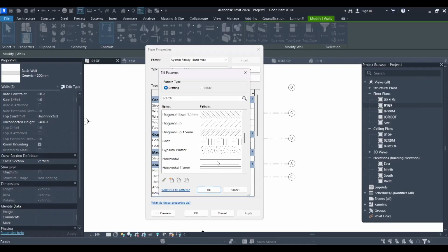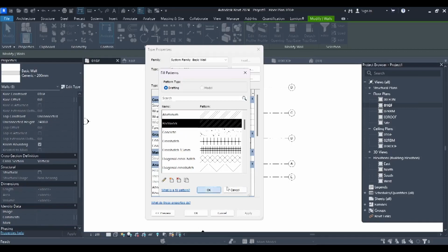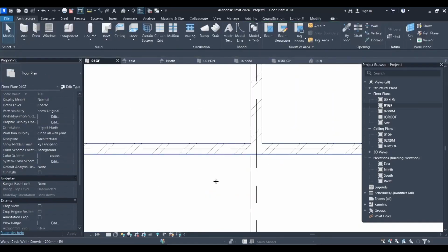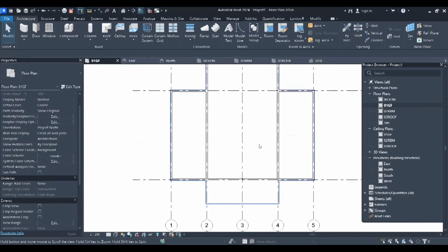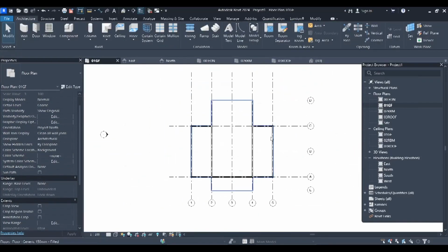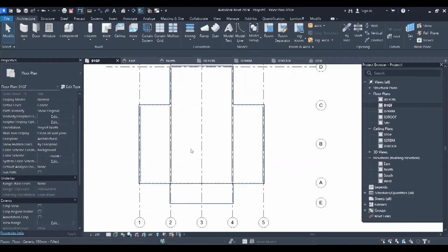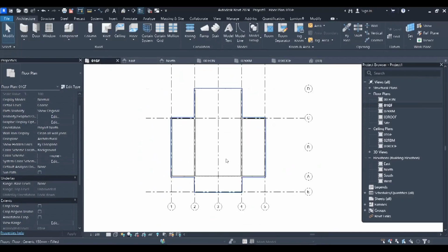Now let me say I want my wall to look like steel, or aluminium, or brick wall. Let me choose brick wall. So exactly, looking at it now, it looks like an ArchiCAD wall. You can choose any pattern. There are many. So that is the floor plan.